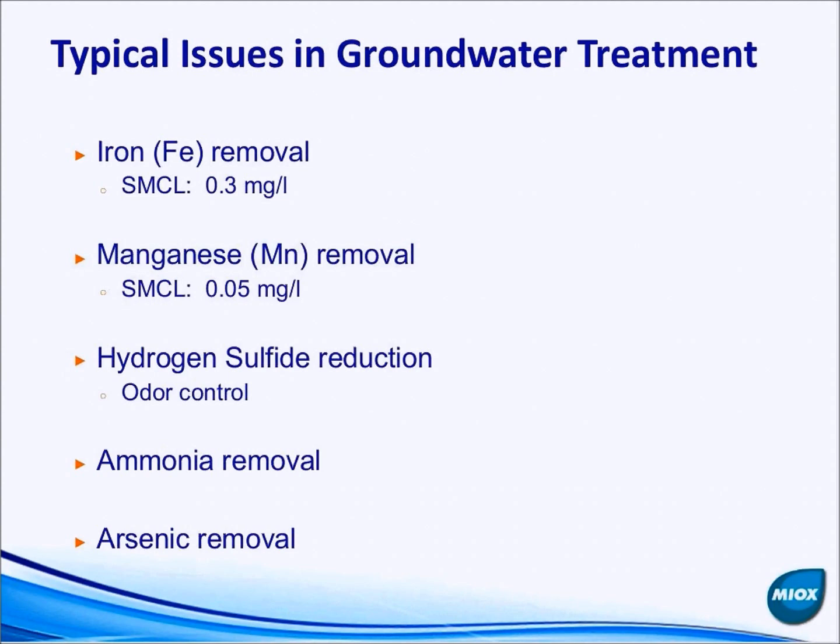Hydrogen sulfide reduction. This is actually kind of an interesting application as well, in that at most levels in which it is found in drinking water, it doesn't present a direct health issue, but it has a horrible odor. It smells like rotten eggs. So you'll get a lot of complaints. Technically, if you're in a situation where the hydrogen sulfide gets high enough, you can run into some health issues. It can cause a mild laxative effect at higher concentrations.